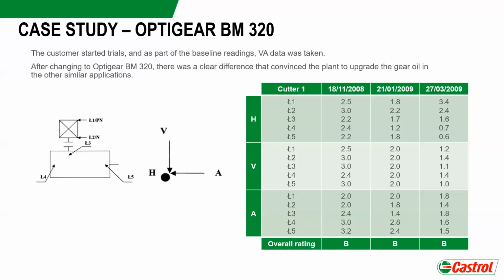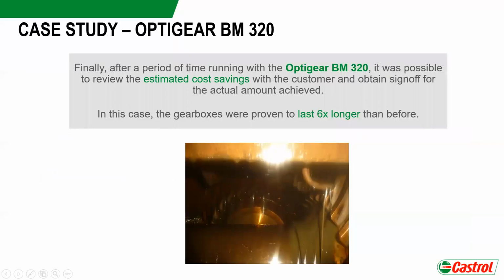So if we go to the next slide, please. Thank you. We can see inside the gearbox there, it's not a great picture, and it doesn't really show us much apart from the fact that we would expect this type of gearbox, being very robust, to last for a long time. The gearboxes only lasted for 6 months before they would break, and they would either need refurbishing in situ, so in place, so the machine has to be shut down, or they would need to be taken out by crane and then stripped in the maintenance workshop on site.